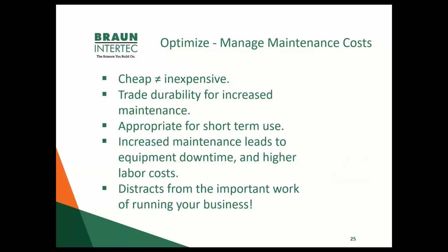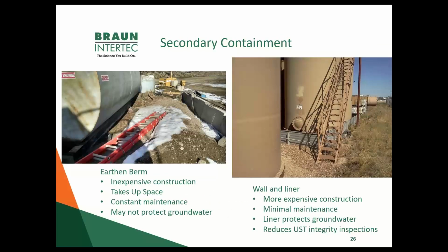So again, if you're looking at optimizing, it's a balance: cheap does not always mean inexpensive. Depending on how long you need to be on site with those materials, you may trade durability for increased maintenance. What works for short-term use may, in the long term, be more expensive and much more of a hassle. So you've got to factor in maintenance and your labor costs for compliance. Secondary containment is a great example of that.